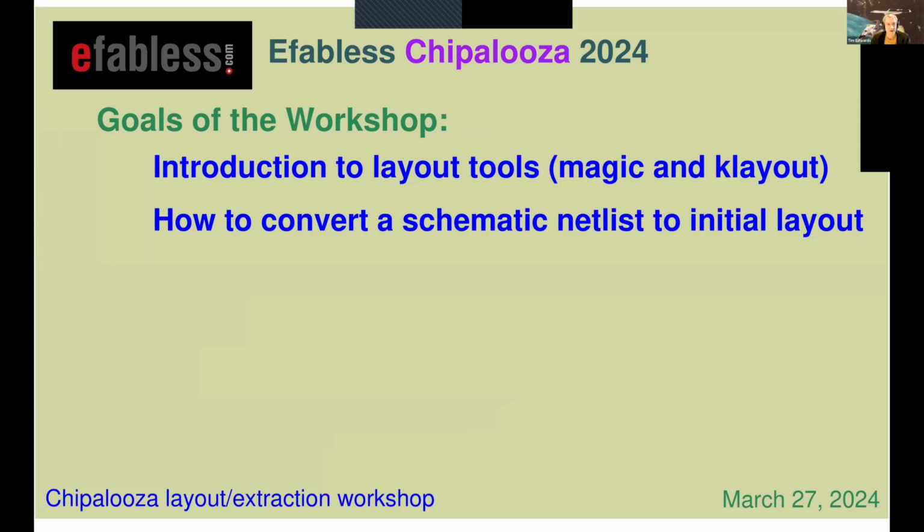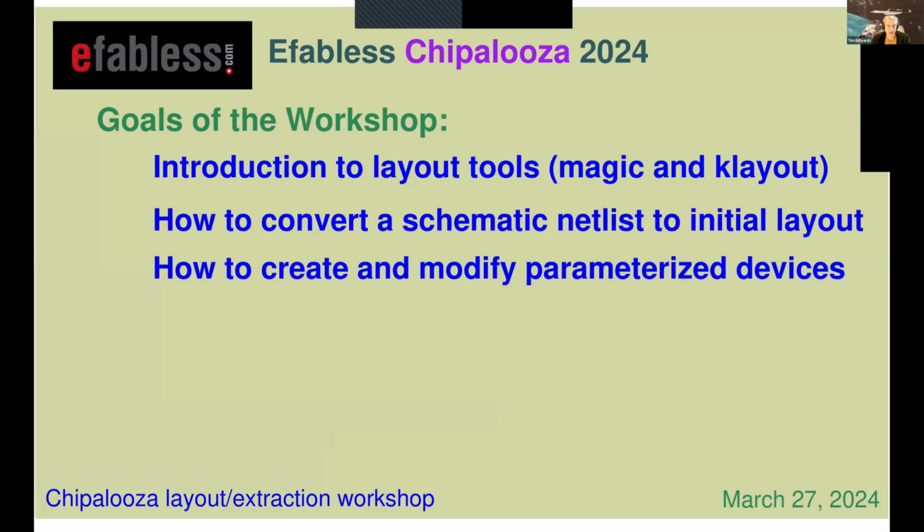There are various tools like Berkeley Analog Generator or FASOC that can do similar things. There's something called ALIGN. You're welcome to play around with them if you are familiar with them. I would not suggest trying to learn one of those tools and ramp up on it in the space of a few days. All of the analog blocks for the Chipalooza Challenge are relatively small and it is feasible to do them in the space of a few weeks with manual layout.